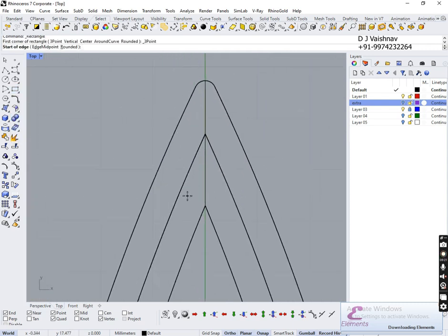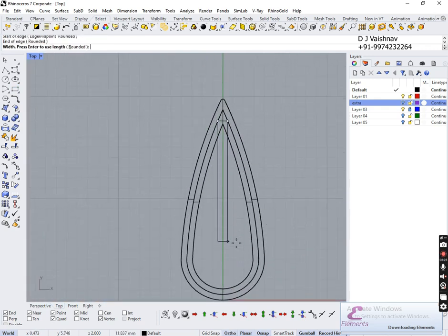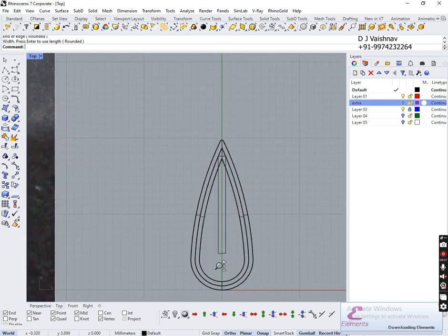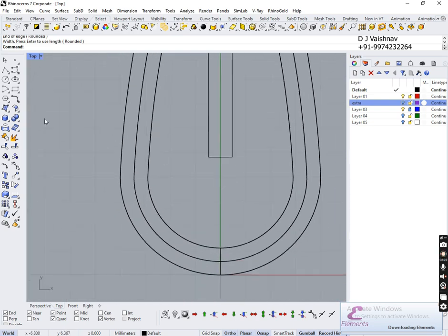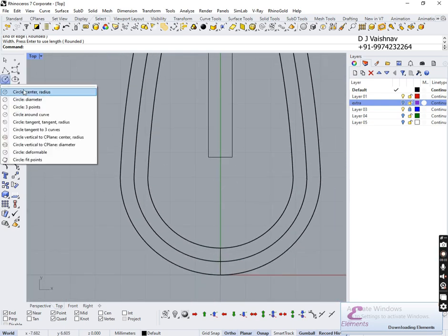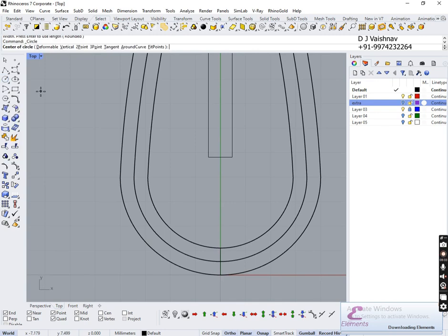This is my first point, this is my second point, and now go downside. Okay, you can also specify proper dimensions. Select the circle and go to circle creation, then click here and type in the radius as required. Bring it little bit down. You can adjust their scaling.